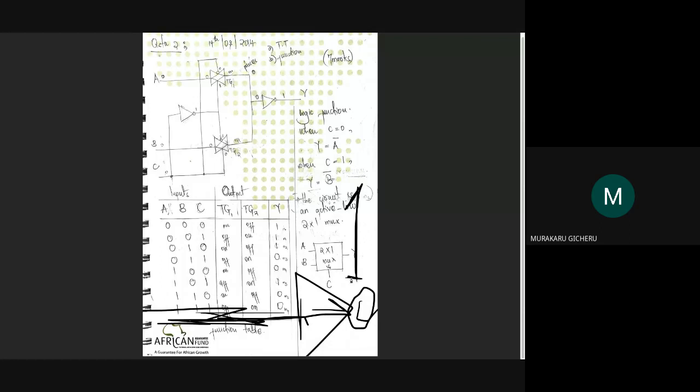So when you connect that control switch to ground, whatever is there will be inverted, and you'll end up with a 1 going into it, and that will activate or inhibit the specific chip or gate that you're working with.